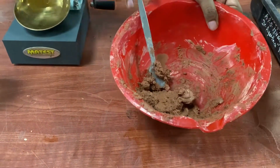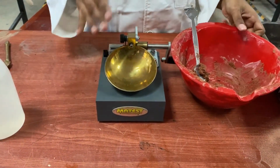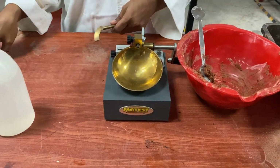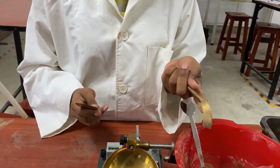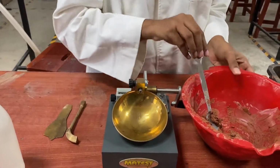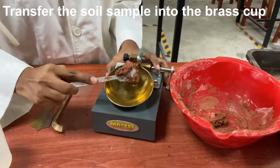Now we need to transfer this sample into this apparatus, make it horizontal, and cut a groove. For that purpose we have two tools: the wedge tool and the grooving tool. We are going to transfer the soil sample into the apparatus.